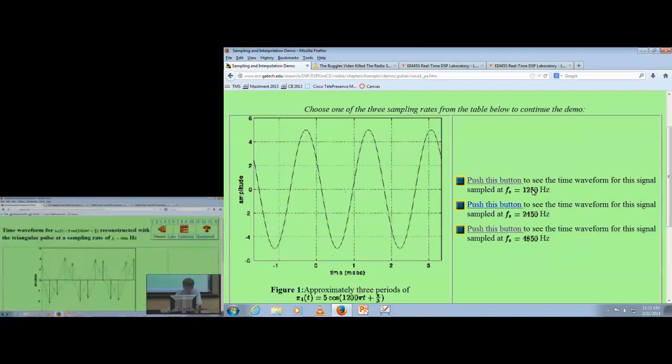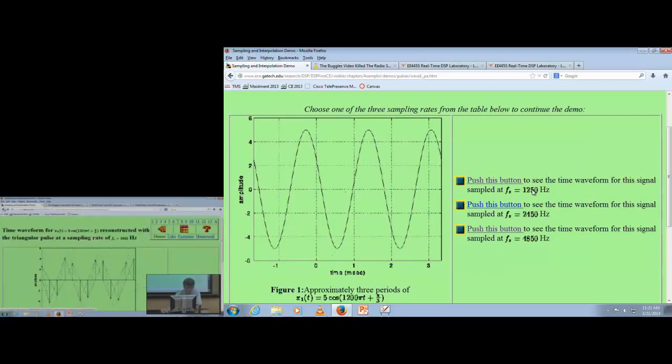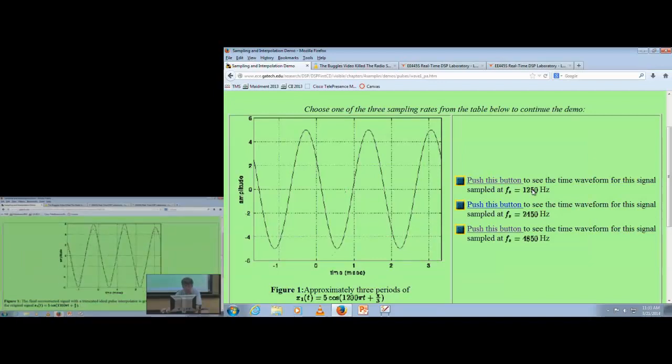Let's do linear interpolation at 2x oversampling. Okay, we're hitting the zero crossings really well. That's good. And we get these jagged corners, again, corresponding to higher frequency content, harmonics. Lastly, truncated sinc. And now it's looking pretty good. So 2x oversampling with the right pulse shape, truncated sinc, looks really good. We're missing a little bit here on the valleys and the peaks. Zero crossings are at the right locations, at least from what we can see.